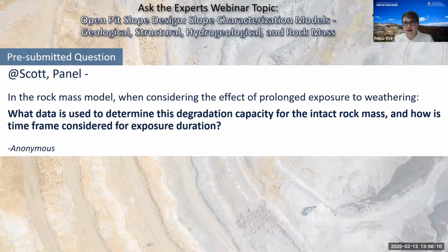We dealt with one site that would react within hours. You had to have it logged at the rig, photographed, sampled and sealed up very quickly, because it was highly expansive clays, and so it would all degrade very quickly. Depending on your mineralogy, you also have to think about how you're collecting the samples and when you're collecting them.